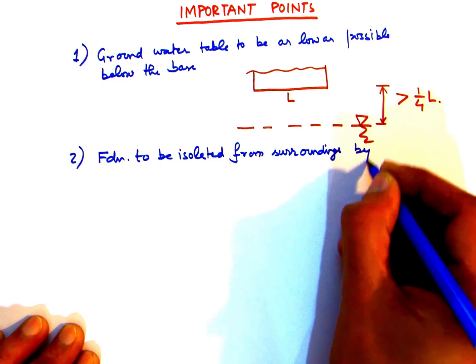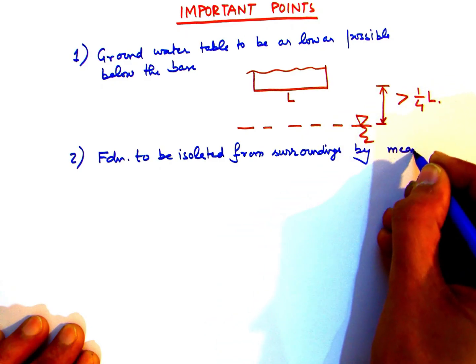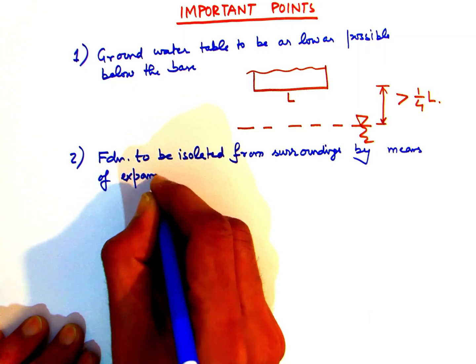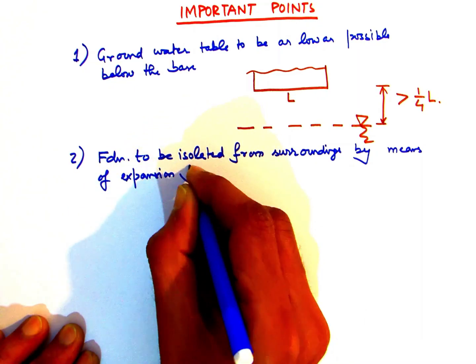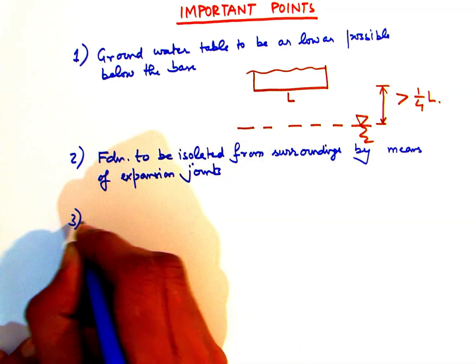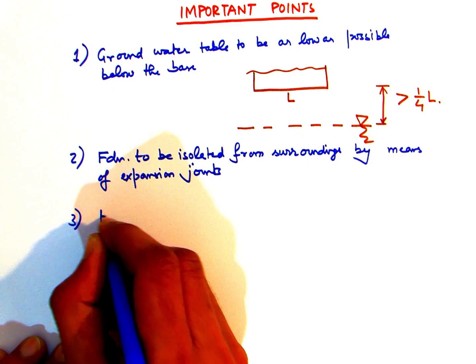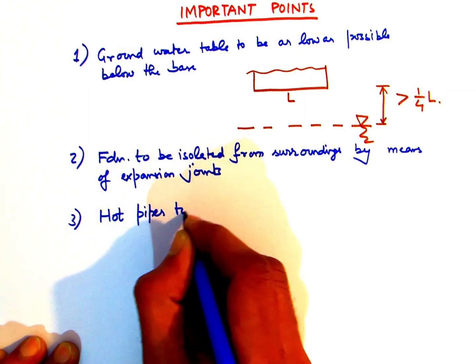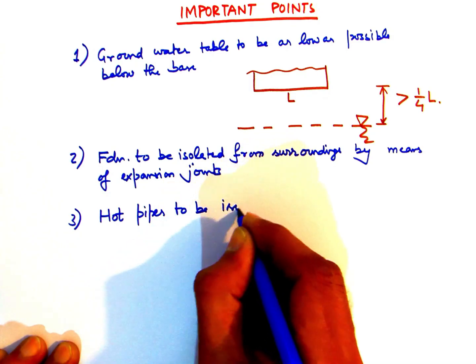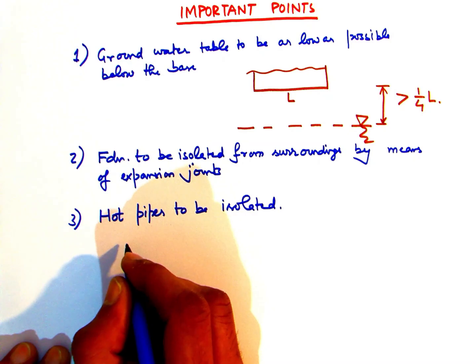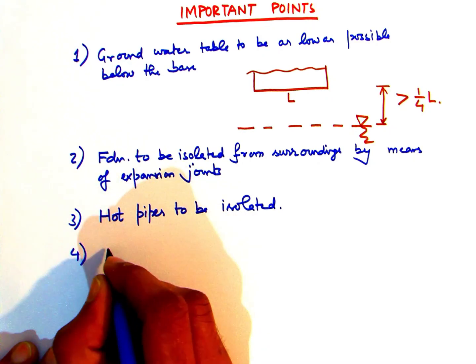However, in situations where the static load coming from the machine and the block together is low, then the geotechnical report might provide reduced allowable net bearing pressures at shallower depths. In any case, the concurrence of the geotechnical engineer must be taken.